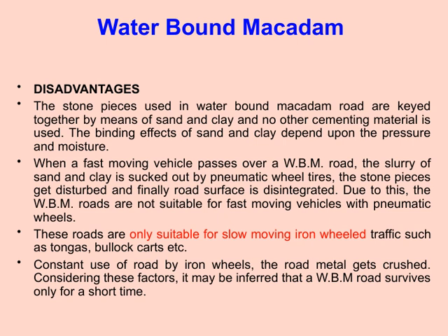Instead, they are better suited for slow-moving traffic, such as tongas or bullock carts, which exert less force on the surface. Additionally, constant use by iron-wheeled vehicles can crush the road metal, further reducing the lifespan of the road. Taking all these factors into account, we can see that WBM roads tend to have a relatively short lifespan, especially under heavy or fast traffic conditions.